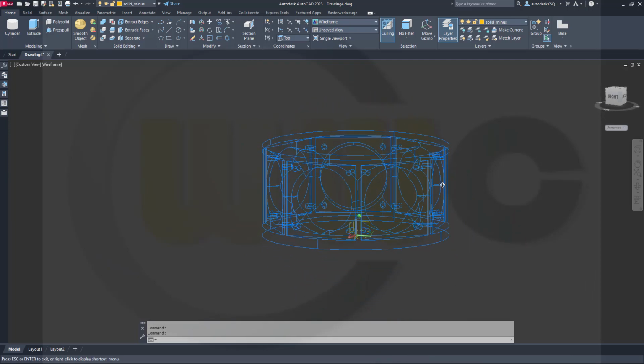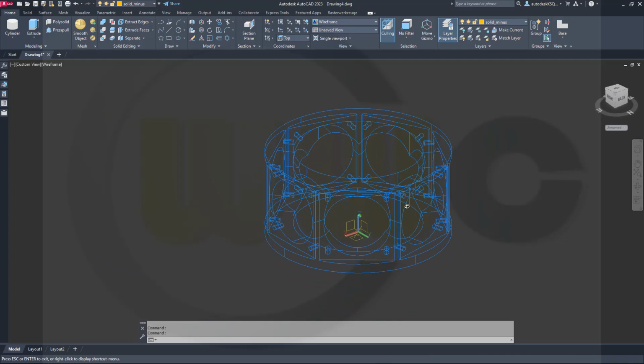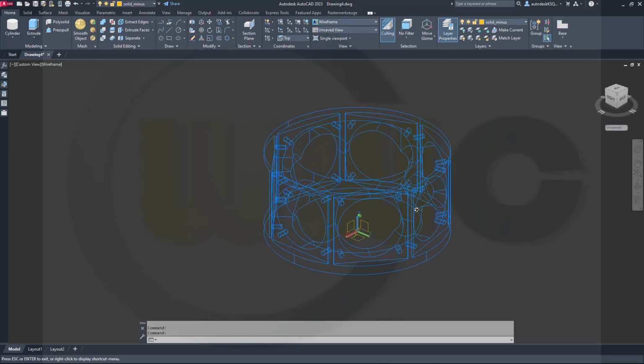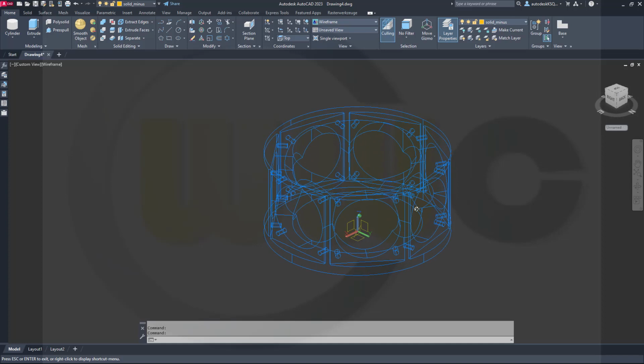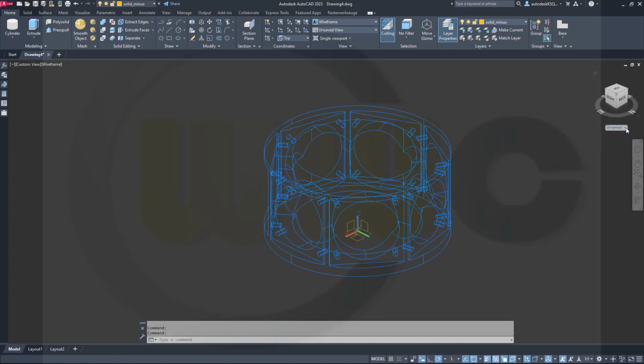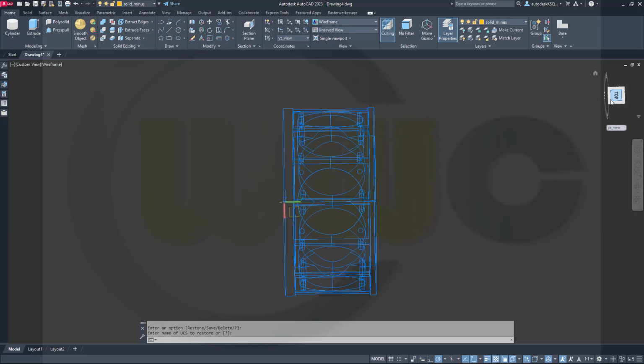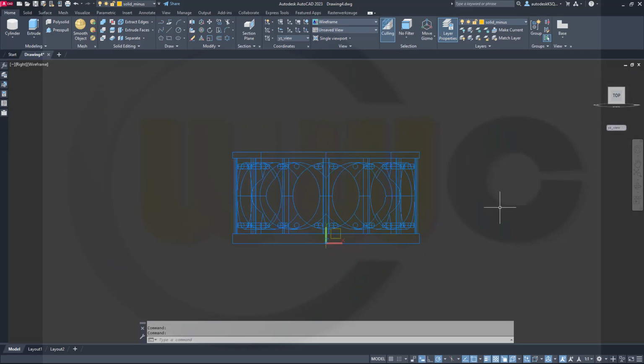What's missing now is that last revolve, and therefore I need another sketch. This time I need a sketch. I could go for a torus as well, but I want to go for a sketch, and that would be again on the YZ view. Let's take a look from the top. And yes, like that, and hide that one here, the blue one.